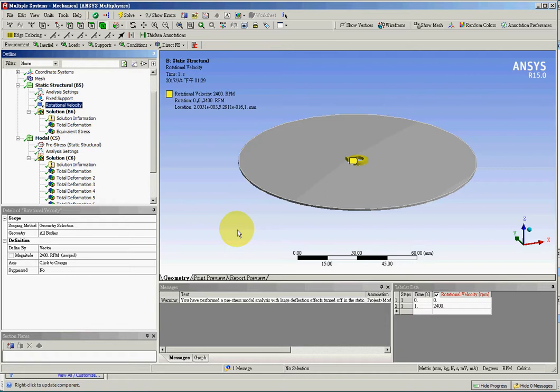So that is very important that you distinguish from external force. If an external force changes the pre-stress condition or the internal stiffness of a structure, then the external force will change natural frequencies. If the external force does not change the stiffness of a structure, then the external force will not affect the natural frequency of the structure.